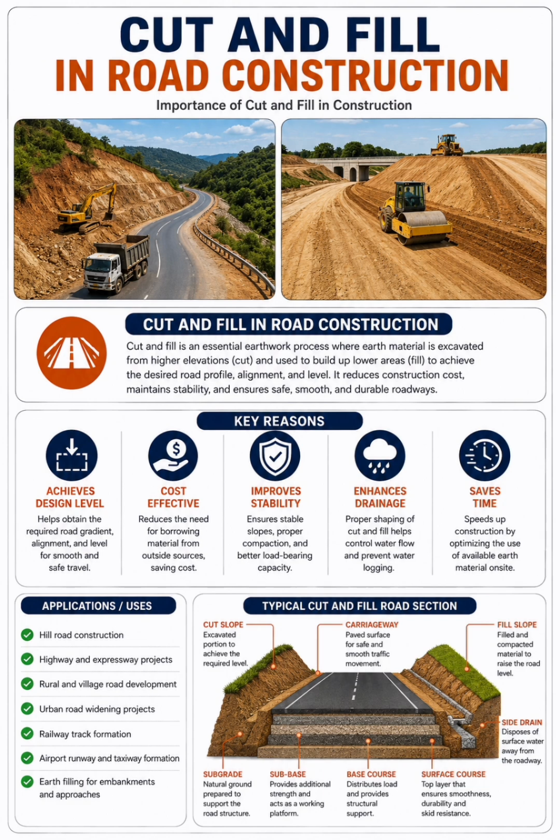Then the next point here is saves time, because it speeds up construction by optimizing the use of available earth material on site. As much as you have your material on site, it actually helps to save the time of going out with your dump truck to get material outside before driving in to the site and dumping, you understand. But since you already have your materials on the site, the one you cut, you can just make use of that and fill. That is if the material is satisfactory, if it passed the standard that is required for the road construction.